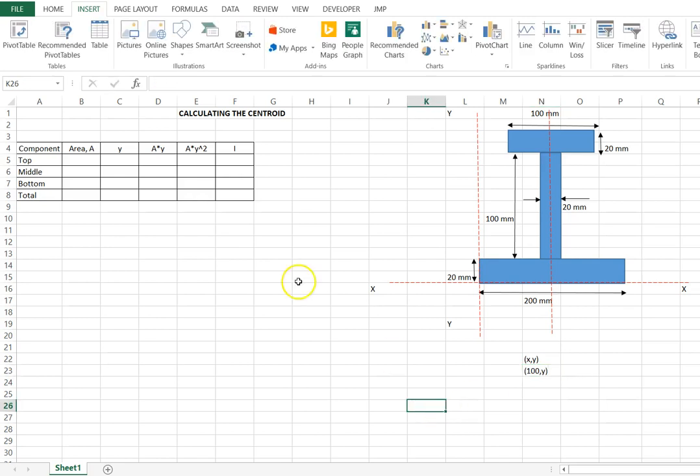So this entire table is what I'm using to calculate the y dimension, right? The y distance, and they're all measured from this x-axis here. Okay. Let me get rid of this for now. All right. So for each figure, we'll find the area and the corresponding center, we'll find the y dimension with respect to the x-axis, the height actually, right?